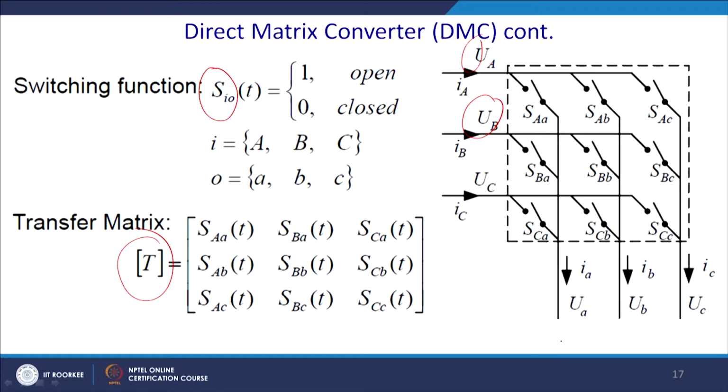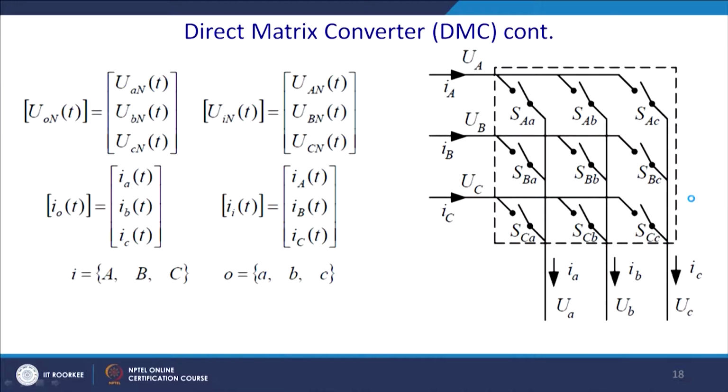If you have a same frequency conversion, then this switch and this switch will be shorted. This is the output voltage matrix, and you can also have asymmetrical configurations. Mostly it can be used for multi-phase electrical machines with more than 3 phases, 5 phase, 6 phase. So, you can have a larger number of output legs also.